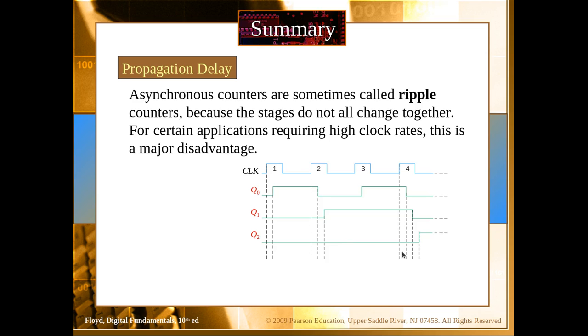Similarly, the third one has 4 times more delay. So the propagation delay increases with each subsequent flip-flop. And for that matter, if we want this assembly of flip-flops to work as a counter, we would like to minimize the delay, or we would like to increase the speed of the clock such that through a number of bits, the total propagation does not increase,